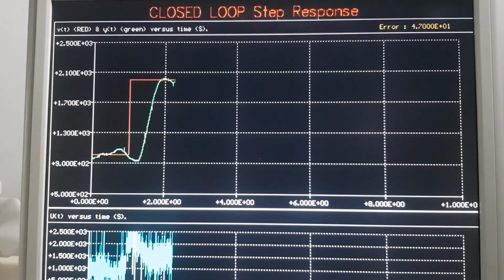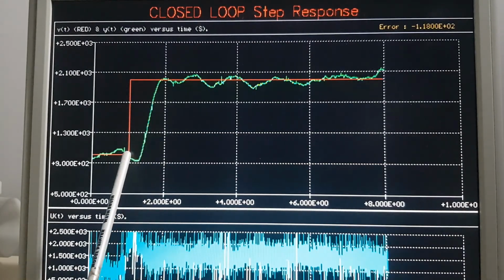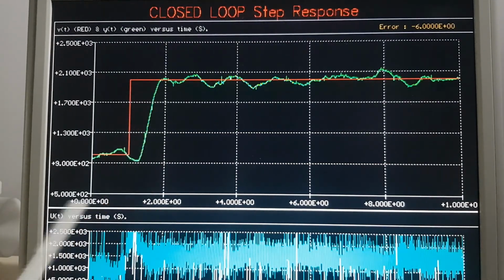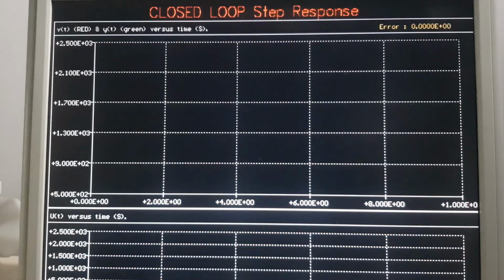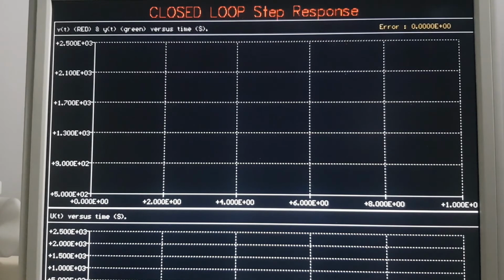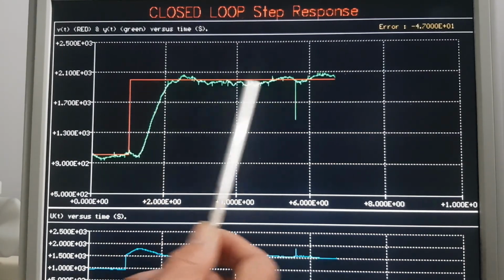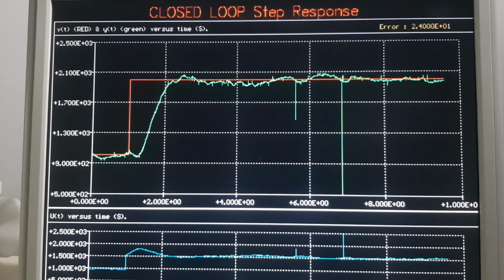So here we go. This is a good little controller, isn't it? Notice it's coming up here, where that dotted line is, that's quite fast for your PID. Let's just compare that back to our PI. Remember our PI, it was 0.6 and 0.8 and 0, so this is our fairly well tuned PI controller. Let's just see where that one comes up. That one's a little bit slower here. So your PID is about 10% faster than your PI.